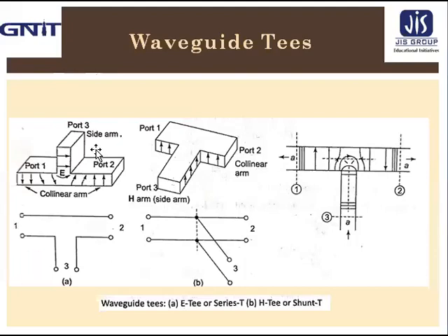They are used to connect a branch or section of the waveguide in series or parallel with the main waveguide transmission line, for providing means of splitting and also of combining power in a waveguide system.